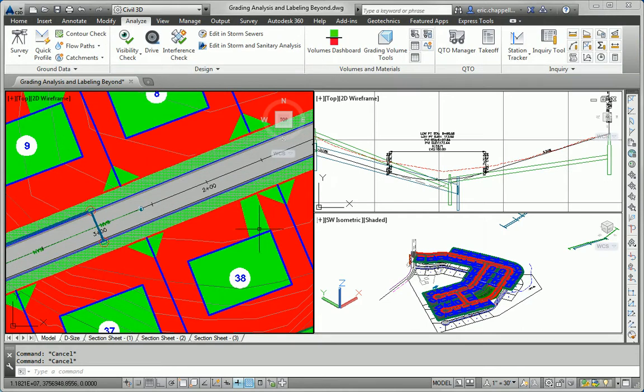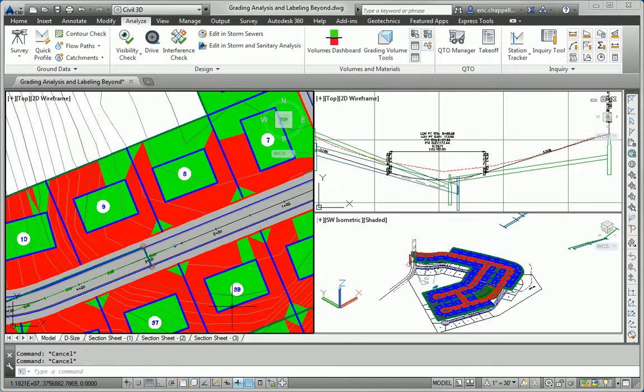And we've got a little bit of green, but it looks like 2 feet wasn't quite enough. So I would go down maybe another foot, try to get enough green in the front of this building pad where I knew I had enough area of acceptable slope to build a driveway. Continue working my way through.